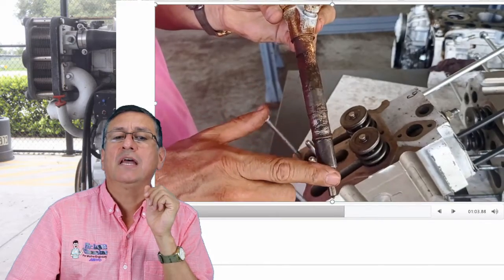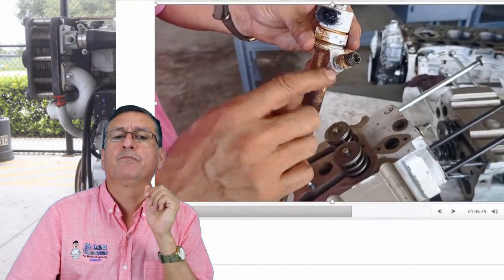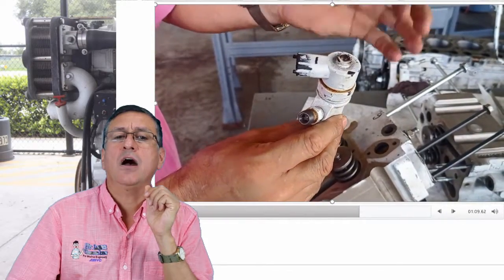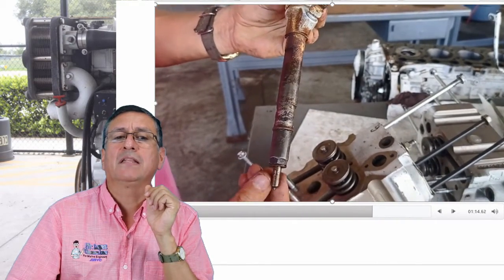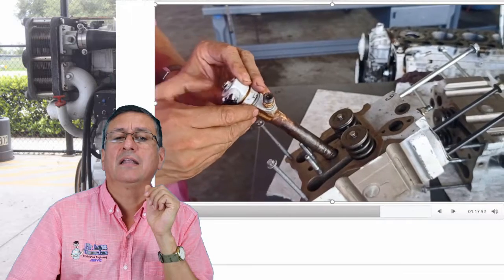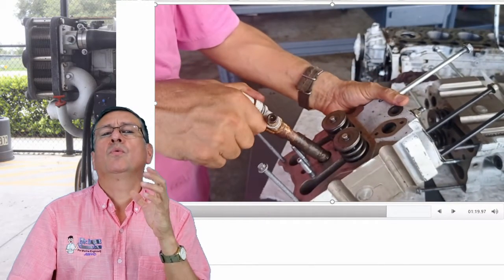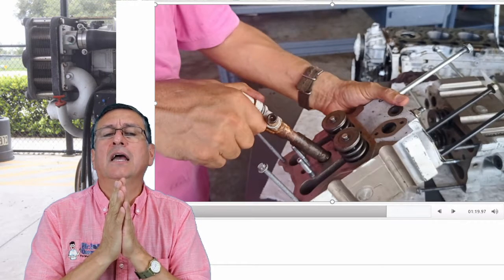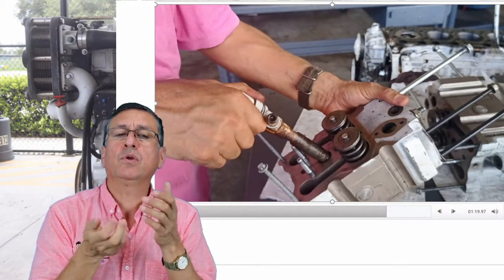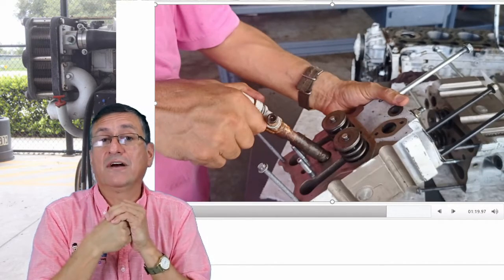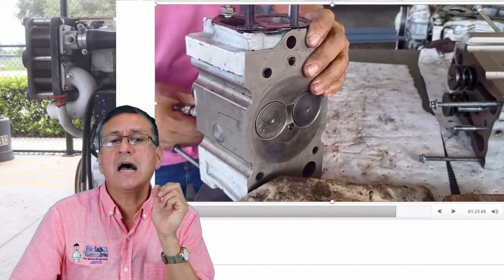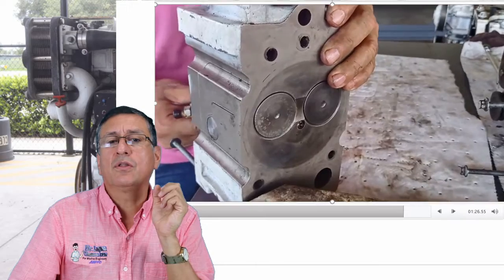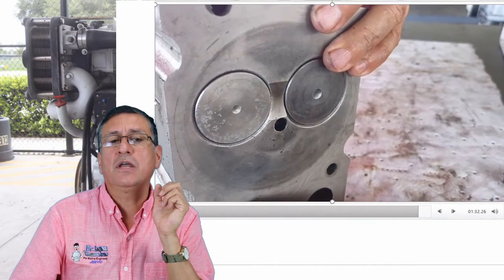Okay, my friends, those elements should be verified, the input, the output, and this is the signal. That element that I have on top is the solenoid, correct? And this is the procedure. Normally when you insert the injector on the head, I recommend covering the body of the injector with grease or with Vaseline if you have Vaseline. Okay, you introduce the injector carefully and you verify that the nozzle goes out through the other side into the combustion chamber. Correct. You verify that the nozzle is going out.